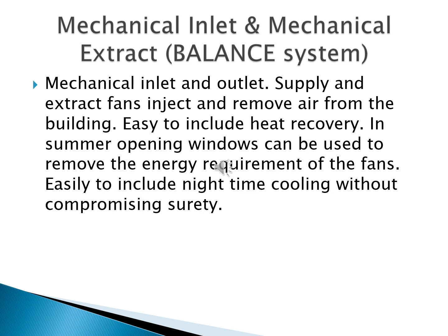Mechanical inlet and mechanical extract, or balance system. It is also called mechanical inlet and outlet. The system extracts and inlets air using mechanical equipment. Supply and extract fans inject and remove air from the building. It is easy to include heat recovery. In summer, opening windows can be used to remove the energy requirement of the fans.